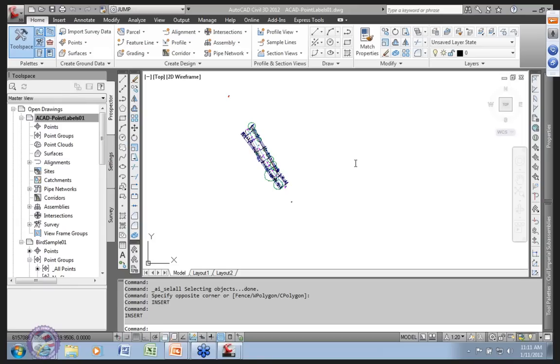Once again, a good example of how Civil 3D data just becomes dumb CAD stuff without too much effort, just following a fairly simple process. The more structured you make this process, the faster it is to do. Once again, the key is producing template files that have all the point groups that you need, tweaked the way you want them in terms of how the labels are arranged, what labels you have, what symbols are employed, etc. The more you work at producing that template that takes your survey database and vomits it out in exactly the right way, that's where you get faster and faster, and better and better and more consistent results with less man hours.